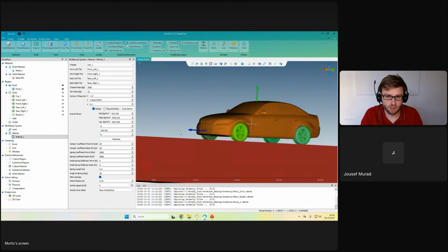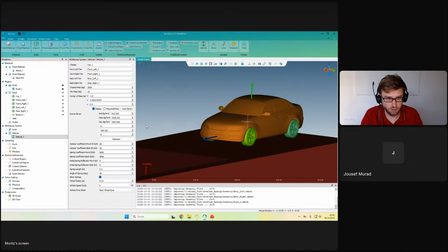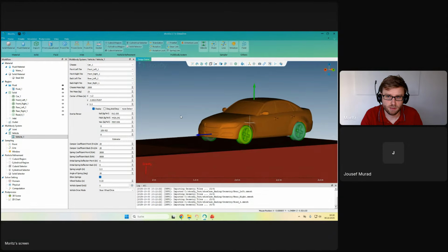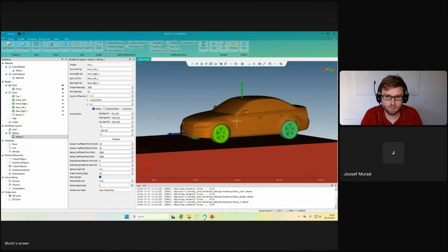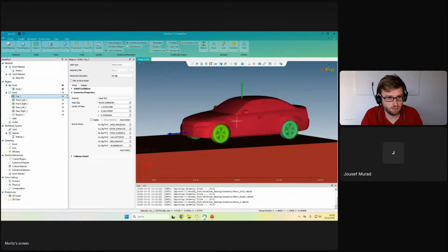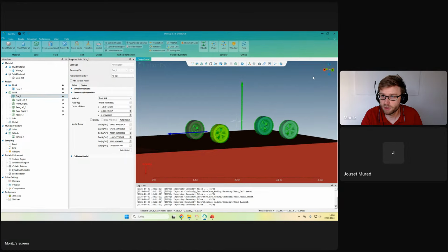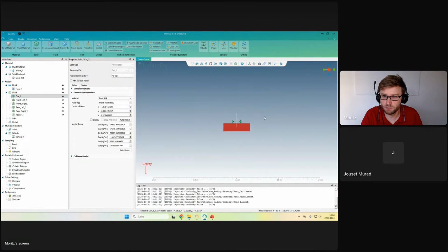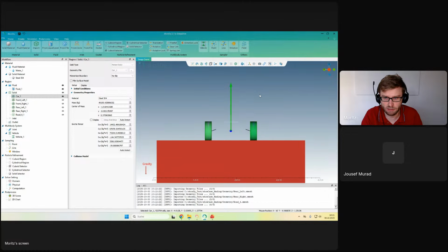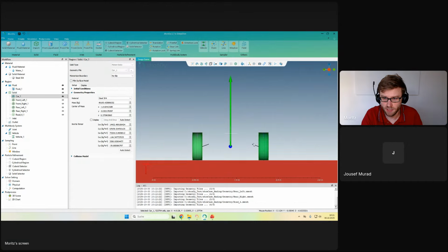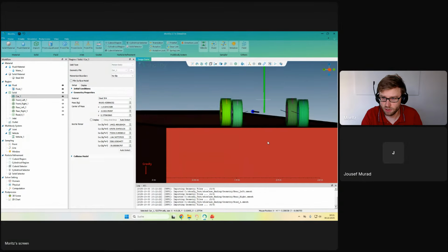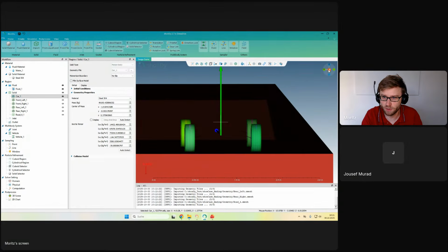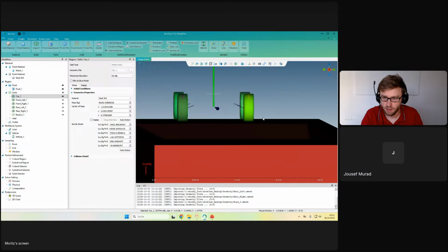And now we have to also define our damper and spring module. It's, let's say, an abstracted form of a spring damper system. We have an analytical model of a double wishbone system. The small blue strings you see are our springs.